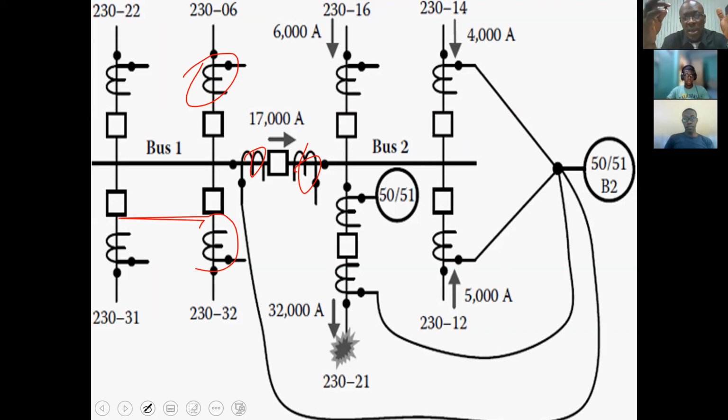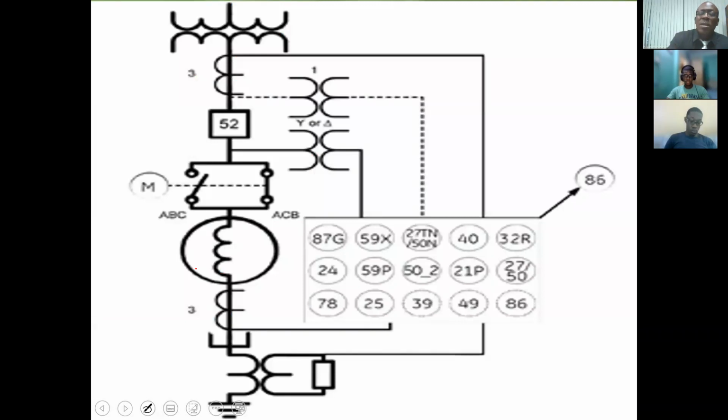You have your relays, you have your CTs connected to your relays, protecting various pieces of equipment. That's the power system. So these are the set of relay numbers that you may have. And here we are showing the PT. So you'd have your PT here. And I keep aging myself, your VTs. And some of these relays, as you will see very soon, will require both inputs.